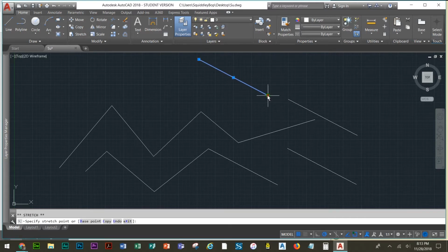So you click and hold, and you can actually see it's showing where it's straight, up and down, or horizontally. That's called a polar snap. It's actually a different button. But here's the object snap. See that end point right there? And there are a bunch of different object snaps, and they can be really handy if you want to go towards the end of something.